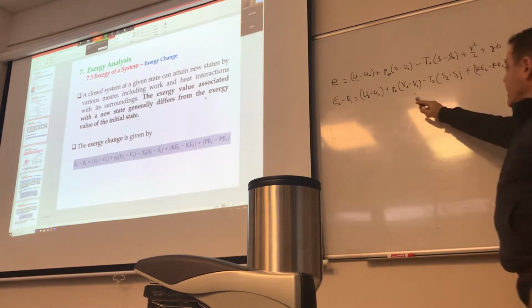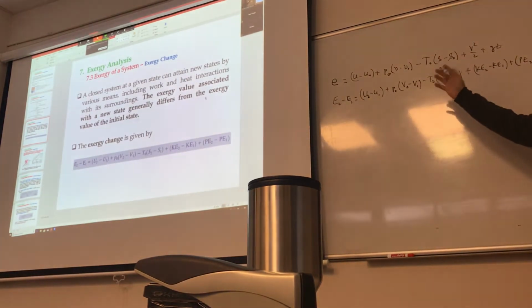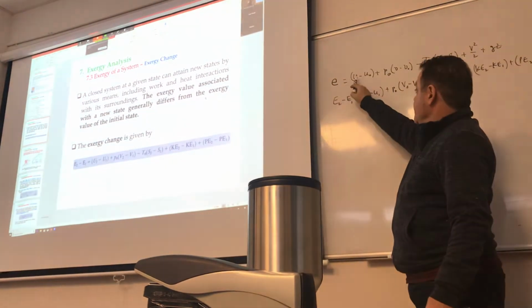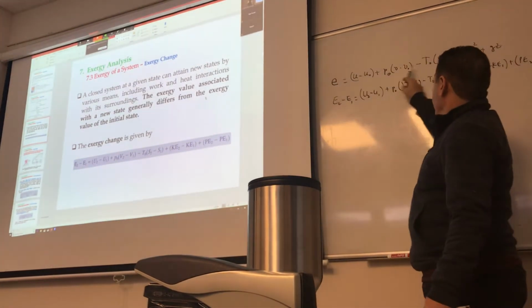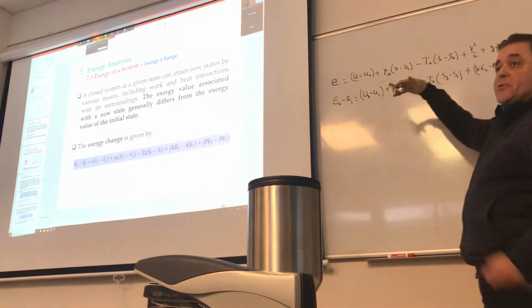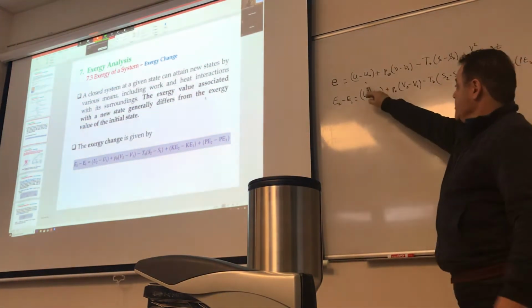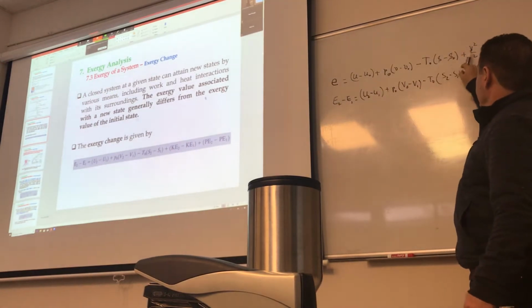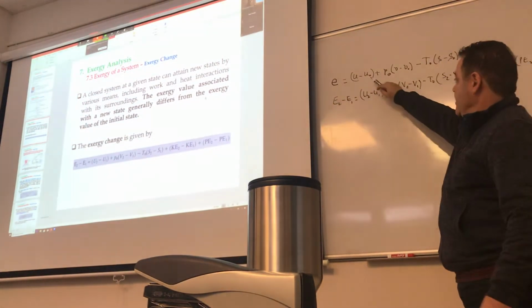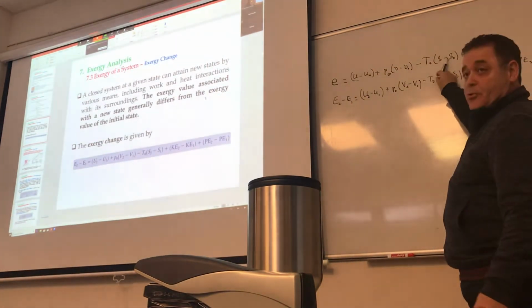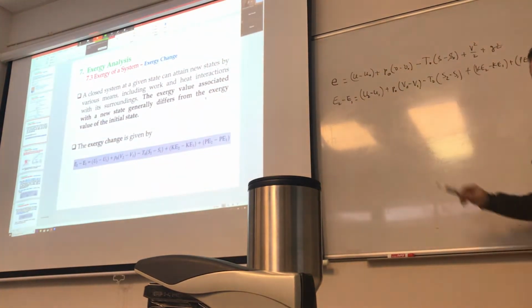You may say, where the heck does this equation come from? It's really not a big deal. You can find what E1 is: this becomes U1, V1, S1, V1 squared, gz1. Then you write another one for E2, in which case this will be U2, V2, S2, and then you subtract the two, and clearly the reference terms will disappear, and the only thing you end up with is the difference.